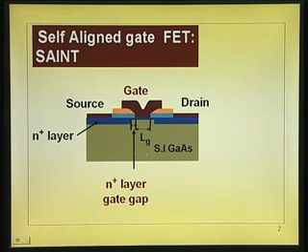This is the self-aligned implantation technology, that is SAINT, where this gap can be adjusted very precisely to the level of 0.2, 0.3 microns, and this is the gate length. So, what we are seeing is the effect of the gate length and this gap on threshold voltage.